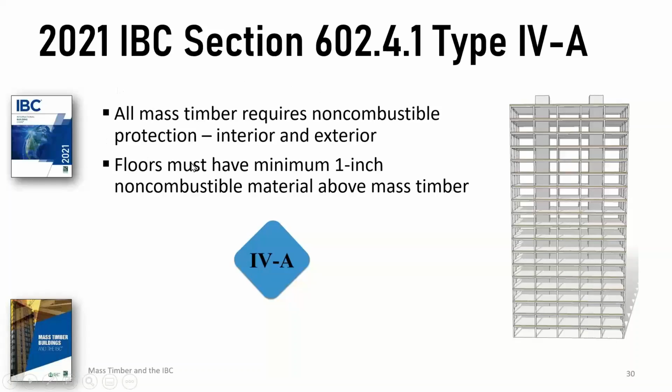Of course, we've already discussed the interior and the exterior covering. The reason the committee included the 1 inch on the mass timber floors was they had not tested anything nor seen any tests that were not done with floors that were protected with concrete. So they decided they needed to keep that as one of the requirements.